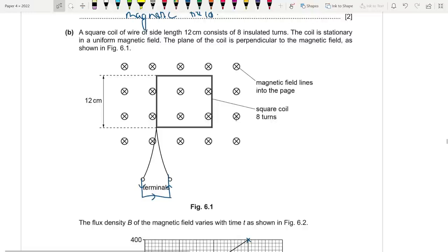You could say the current in the magnetic field. Since there's a current flowing here, it is in the presence of another magnetic field, right? So the coil will now experience a force. Since current is flowing in the coil now, it will experience a force. Now remember that according to Lenz's law, the EMF will be induced in such a way as to oppose the change causing it. Do you understand?